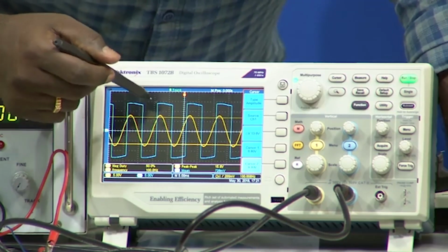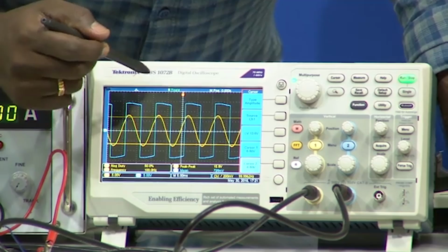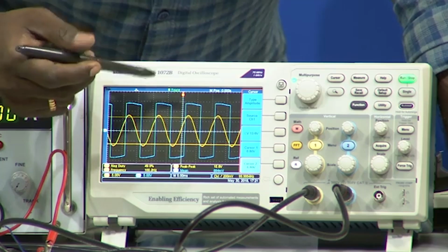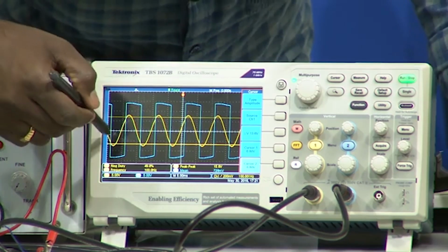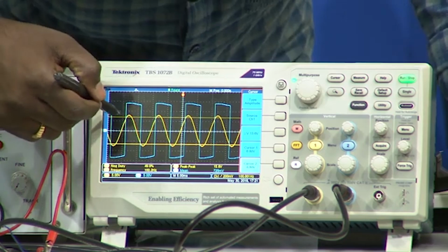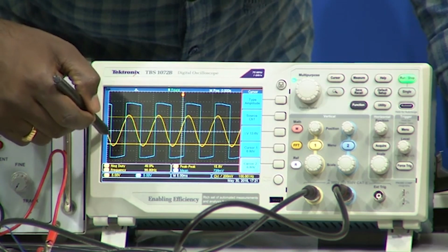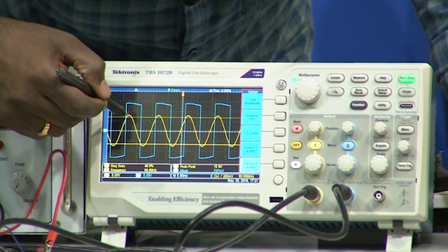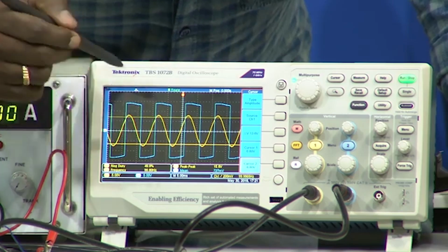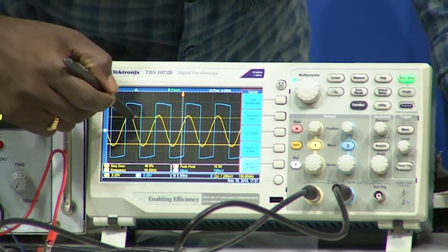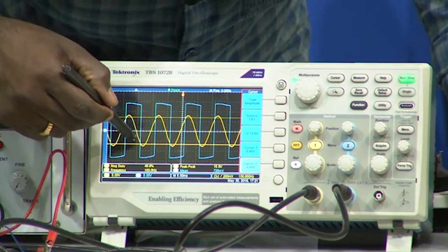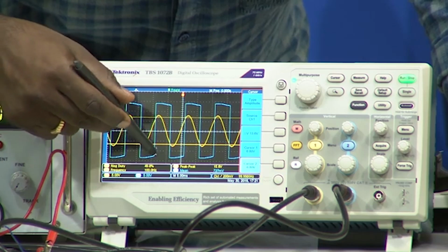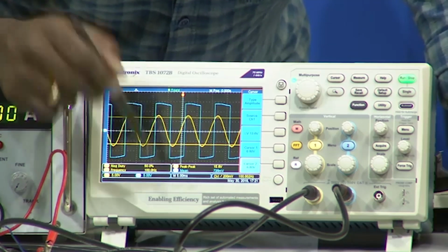Now, is it switching on when the input is greater than 6.8, the higher threshold value? Why do we not check? See the yellow line, this is our higher threshold, this is lower threshold, this is the input voltage. Now, when the input is greater than this particular value, observe here, it has gone to plus VCC, right. Again when the input is lower than the minus VTL, it has gone to minus VCC. So, it is following the same everywhere.